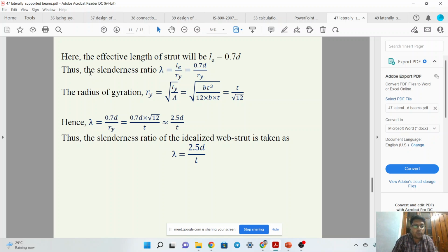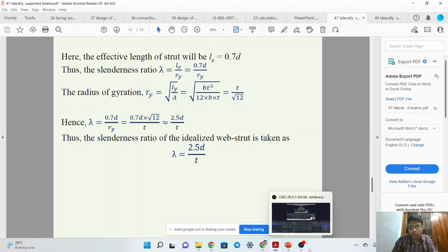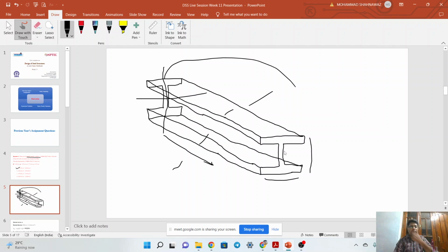Yes. So see, what is the slenderness ratio? The slenderness ratio is L upon Ry. Try to understand the mechanism of the problem. Let us suppose you are going to fix its cross section, so its cross section is not changing, and you are increasing the length of this member. A time will come when it will start acting like a wire, if its length is too long compared to its cross sectional dimension. It will behave like a wire.